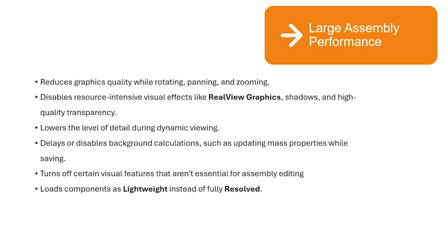I'm not sure how many of you are familiar with the lightweight feature in SOLIDWORKS. So large assembly settings loads your components as lightweight instead of resolved. Just a quick explanation for you guys, the difference between resolved and lightweights.